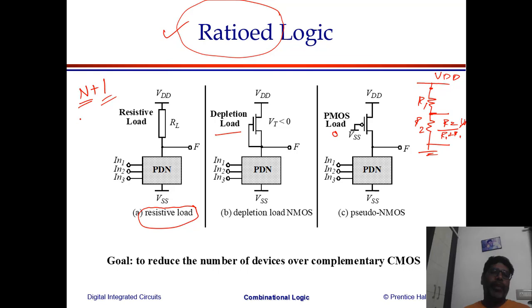So at the maximum it consumes n plus 1 number of transistors. So when I go for ratioed logic, the transistor count gets reduced, which means the area gets reduced. Thereby, wherever the area constraint prevails, I can think of using this ratioed logic. In fact, this method was introduced keeping in mind to reduce the static CMOS transistor count to a very low value.